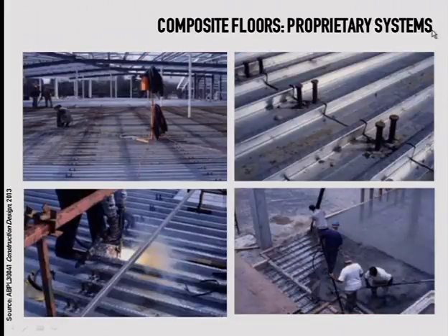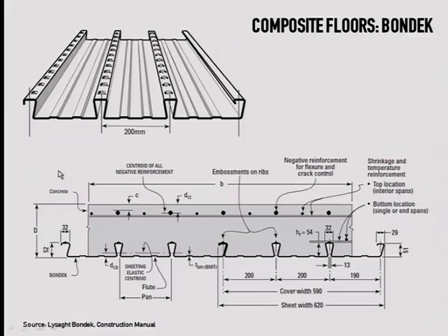And here you see images of these shear connectors, and when the concrete is poured. But I'd like to show you also, if you look into the Bondek catalog, you'll find a lot of nice details and examples. Again, you see this corrugated profile is completely lost. When the concrete is poured, the two elements combine together and participate together to resist the tensional forces.